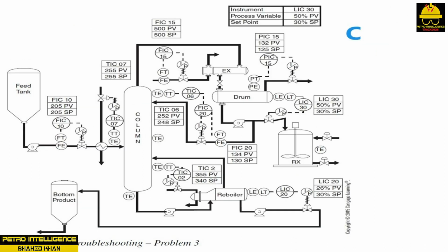In Picture C, a full-scale process upset is occurring. The initial problem was the partial failure of the steam valve, TIC2. Look at the other process variables affected by the higher bottom temperature on the column. Problems in a distillation column typically include feed composition changes, puking, flooding, and equipment or instrumentation failure. The feed has a specific composition. It may be a binary or ternary mixture. It must be controlled to ensure a uniform operation. Puking is a problem that can upset trays, push products up or down the column or out the overhead line.